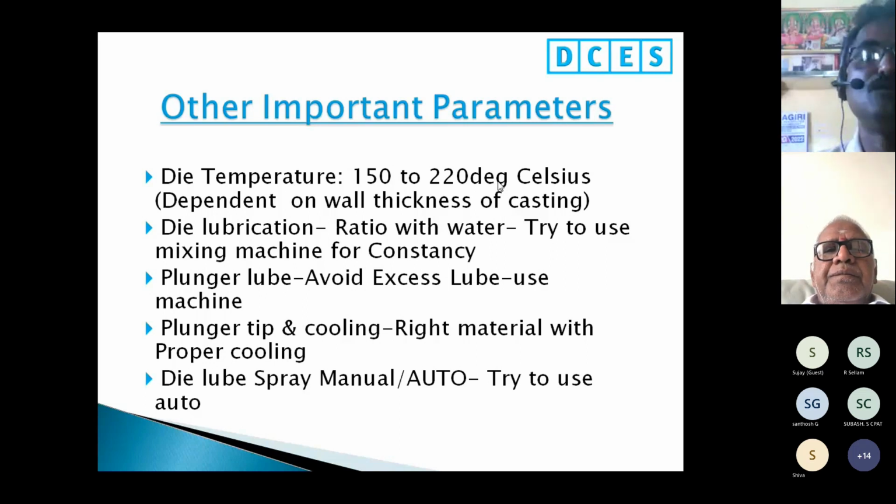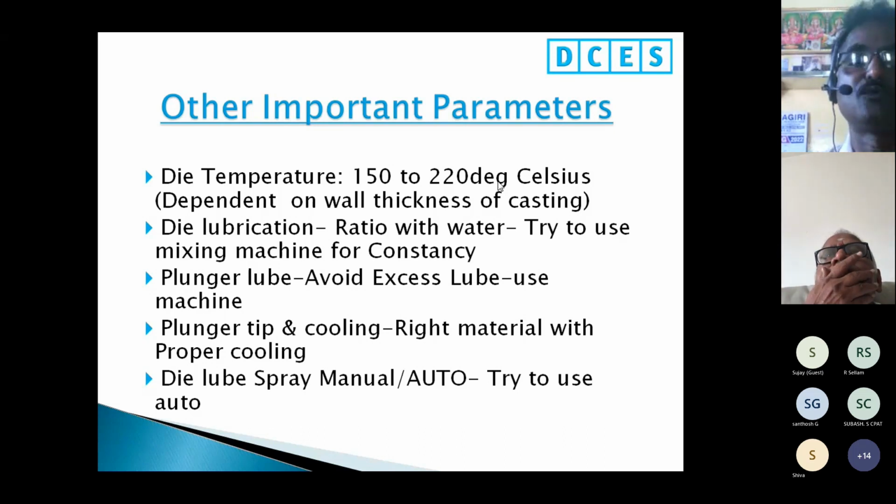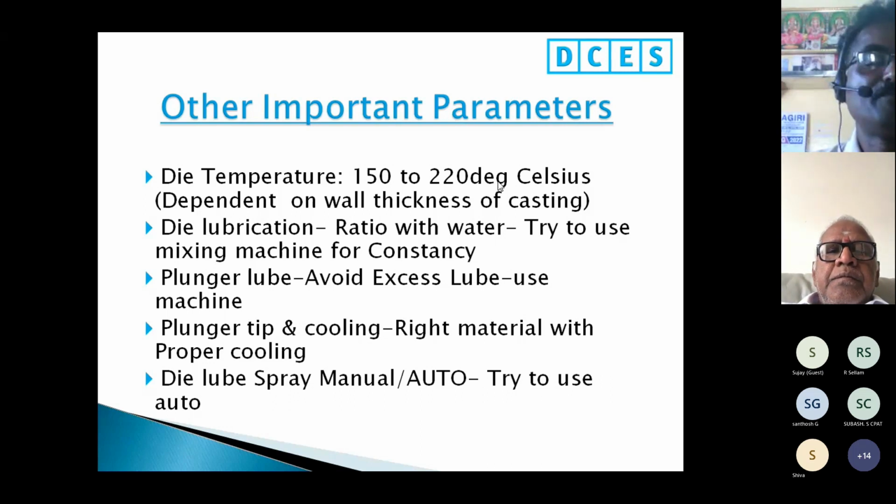When you use excess lubrication, we lose money, and the lubrication oil will also go into the shot sleeve and mix with the material. It will create porosity problems. So always try to use the plunger lubrication machine. It will give you cost reduction and also quality improvement, without any problems.